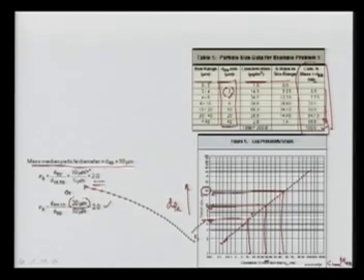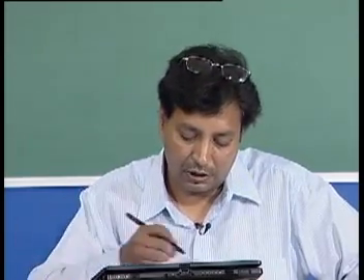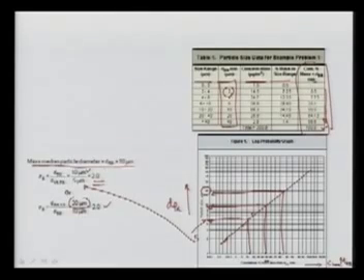So you can see what we have done is we had the data, and we could say the particle size distribution was log normally distributed, and the mass median particle diameter was, I should say, 10 micron, sorry, as you can see here, and the geometric standard deviation was 2.